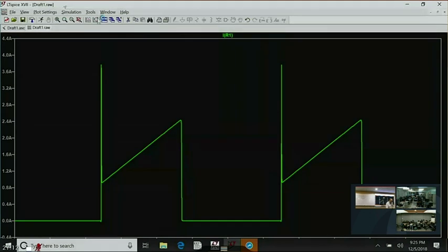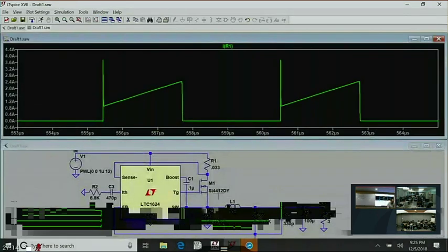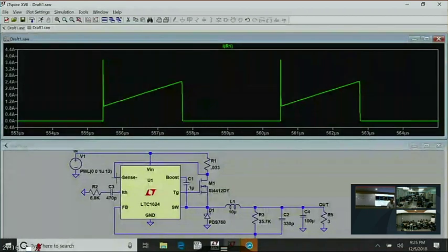That's not good. Anyway, you'll notice that in this circuit, there is no RC filter in front of the current sense amp. There's none there. It isn't necessary because instead of RC filtering, this controller implements high-speed blanking. That is, the current sense amplifier is momentarily shorted to ground.